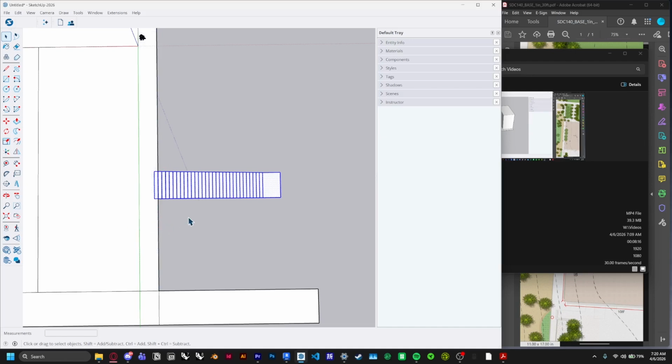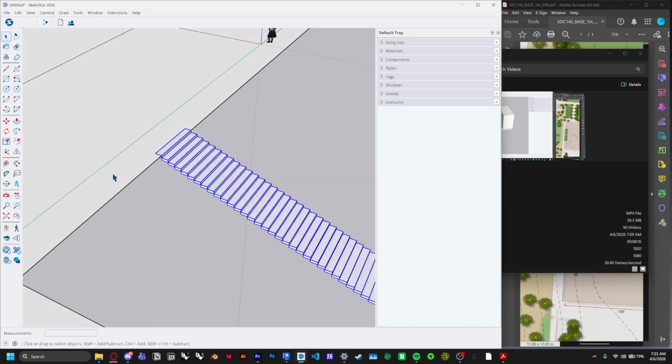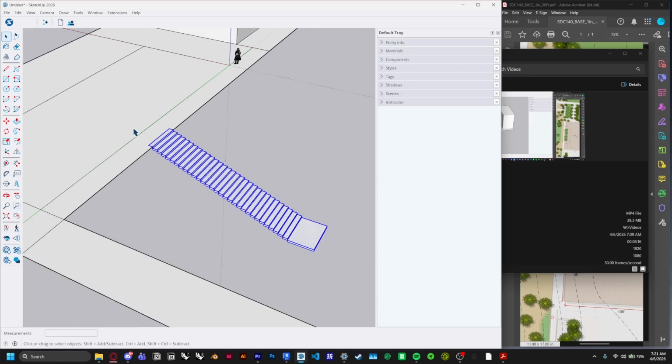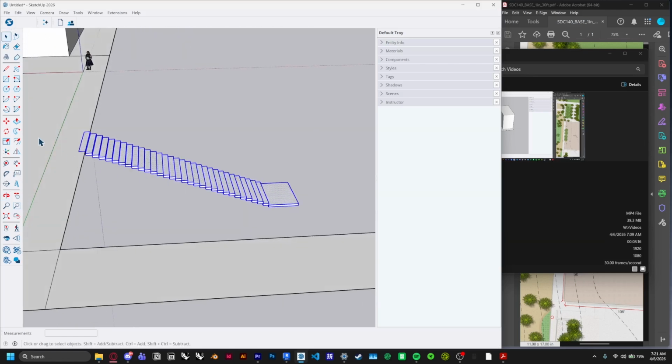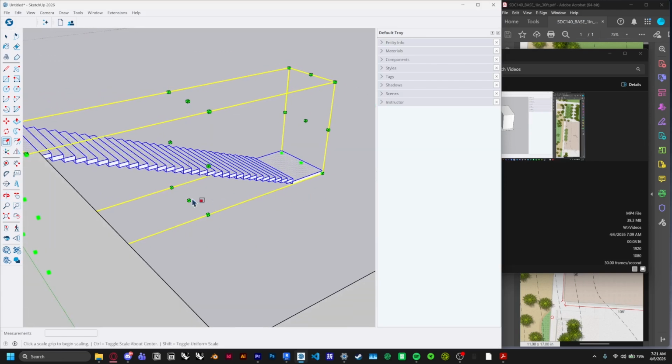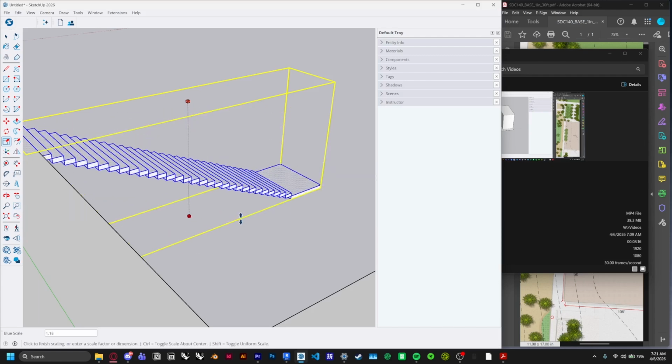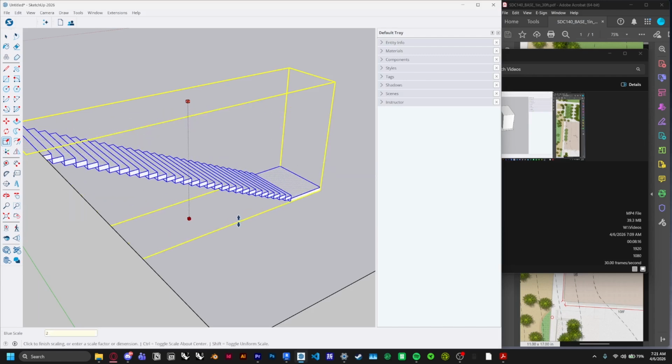Also, make sure that no blue is highlighted when you are selecting these surfaces. Now, click on the Scale tool. It's 2 below the Move and 1 below the Rotate, so once, and it will create this bounding box around your stair objects. To make it 25 feet, click on the bottom center green cube down here just once, and then you can move it to be 25 feet.